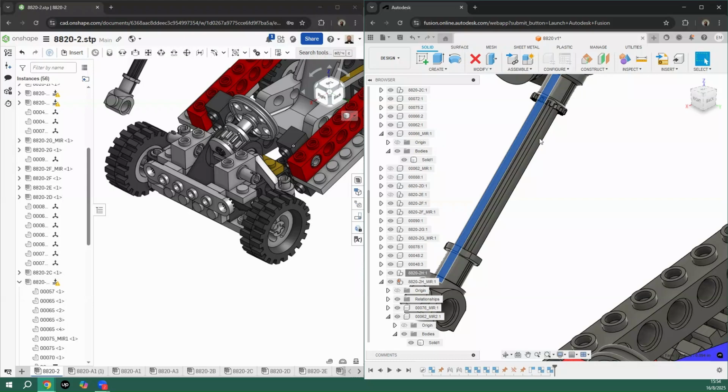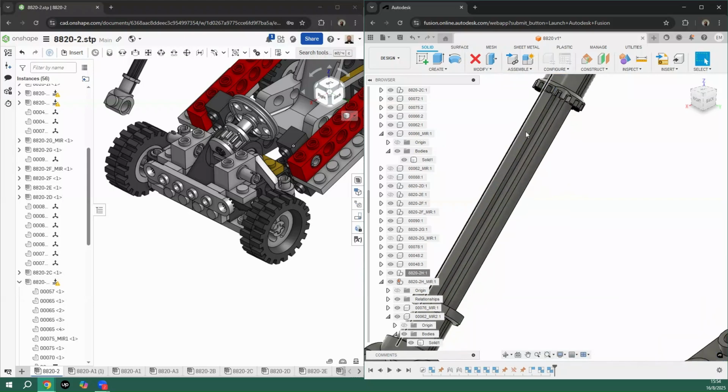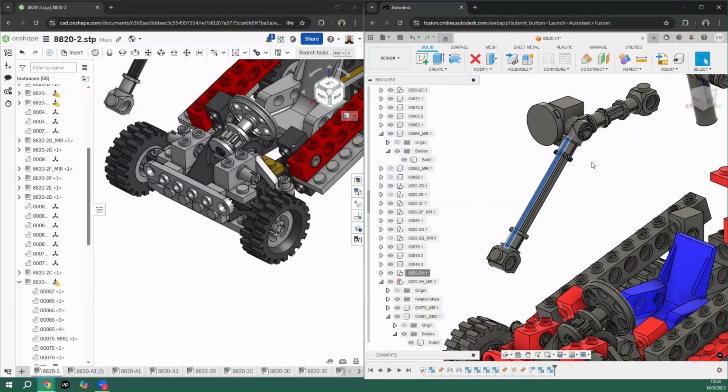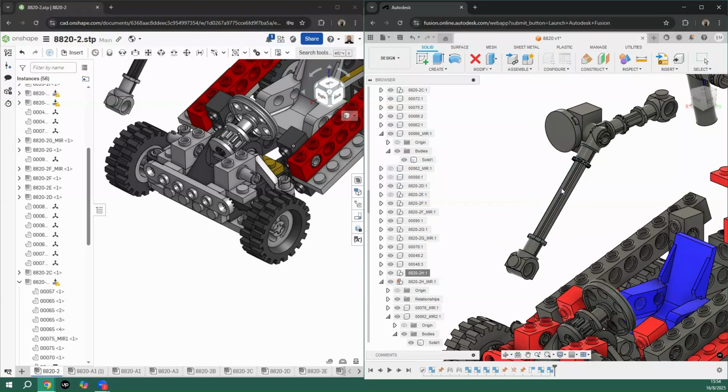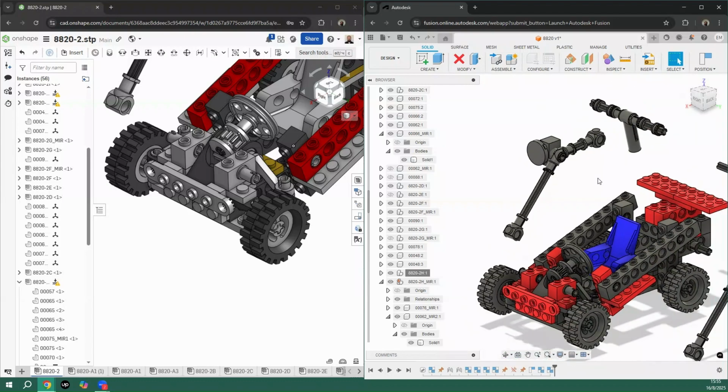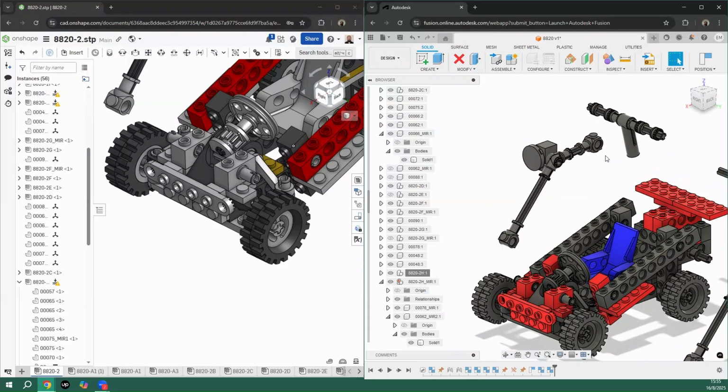At the beginning I was grounding this component, but the problem is that the component is now grounded also for the main assembly. So this section here was not movable, so I had to enter inside the subassembly and remove the pin condition. Now it can move everything together. It was tying up the entire rest of the group just because of that condition.